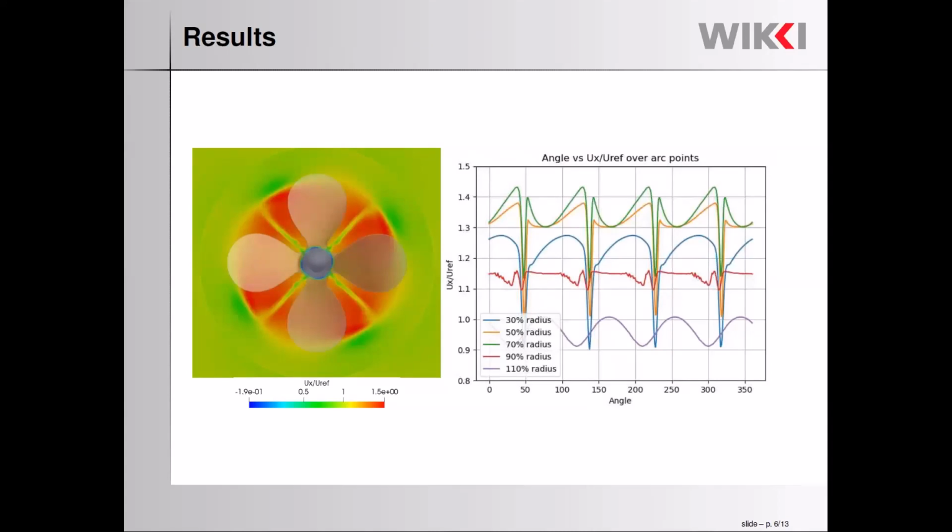There is something, especially when I was looking at the Q isocontour with these vortices, they dissipate quite quickly when you leave the MRF zone into the static zone. Yes, but I'm expecting that this is because there is a jump of 2 to 3 in the volume of the cells, because this is already a very big mesh, and I was not really able to afford many more in the far field.